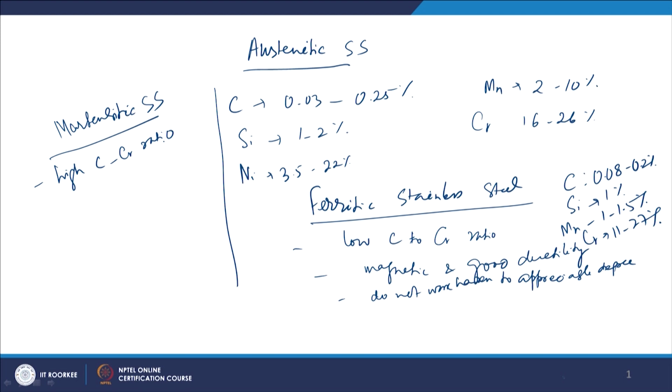They are the hardenable type of material and can be hardened by heat treatment because of the high carbon to chromium ratio. Then they are magnetic in all conditions, they have the best thermal conductivity among all, and they can be cold worked without much difficulty.